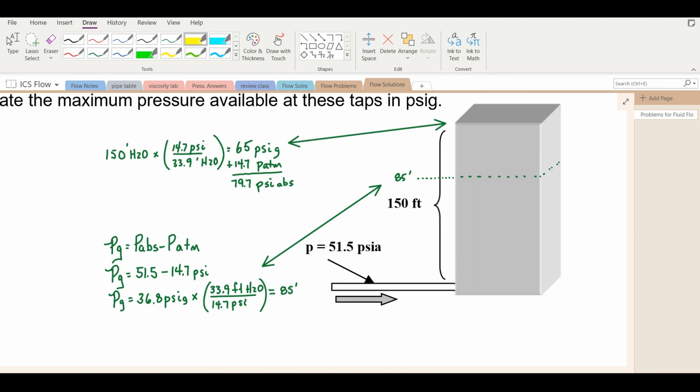What to do? Well, they have to have their own pumps to supplement city water pressure. And then they would have a reservoir on the top of their building. In the event that, say, power went out and the apartment building's pumps went out, the people can't be starved of water, so they pump it up to a reservoir on the top of the tall building, which feeds the floors below. And then when the electricity comes back on, the pumps can refill the reservoir on the top floor. So this will be a good place to stop for this first lecture on solving problems in flow. We have one more lecture involving problems 16 through 21.